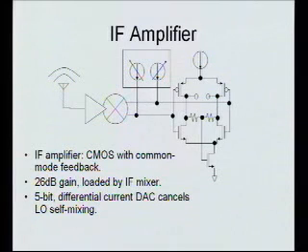So to suppress that effect, there's a DC offset correction, and pretty much every direct conversion receiver out there has one of these. Sometimes they act kind of like AC coupling, with some sort of slow loop acting all the time. But usually you can get away with a calibration, because usually that self-mixing term doesn't change very fast. So you can just measure the DC, insert a correction that matches it, zero it out, and then start receiving data. Certainly most cell phones do that. So that's what I did here. This is just a little differential current DAC. You can just program in some offset to cancel out the DC offset coming out of the mixer.